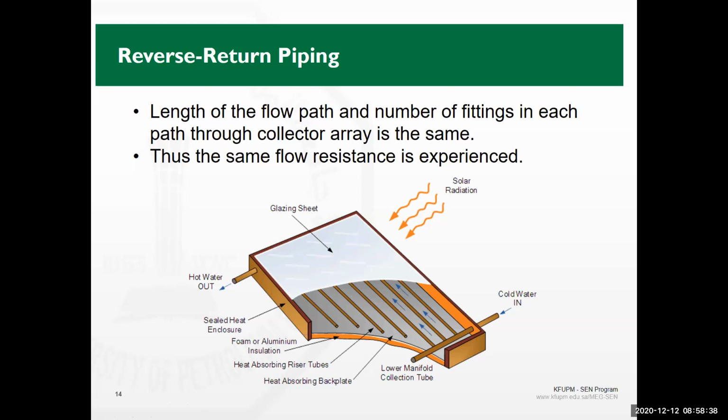Normally for flat plate collectors, the inlets and outlets are something like, I remember the units that we recently bought, a couple of units of flat plate collectors, and I think there are 4 units that we bought. We have connected 2 of them. Again, this is all in our research area in the beach facility. And the outlet here, I'm trying to recall, I think it was something like either 3/4 or 1 inch diameter metallic pipes. After that, you either continue with metallic pipes, which are costly, but normally what we do is just use a connector, and then we connect our PVC systems.